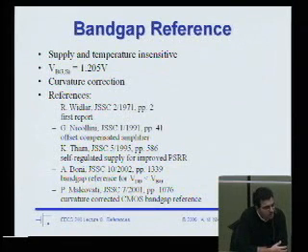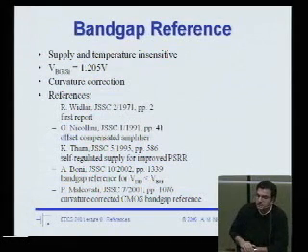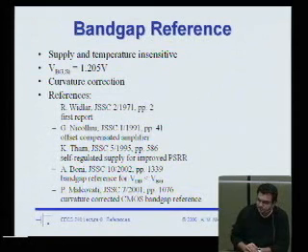If it were just a matter of lithography, we could probably do really well, right? But sheet resistance of poly varies, sheet resistance of metal layers varies, sheet resistance of the substrate varies. So absolute resistors are actually very imprecise.